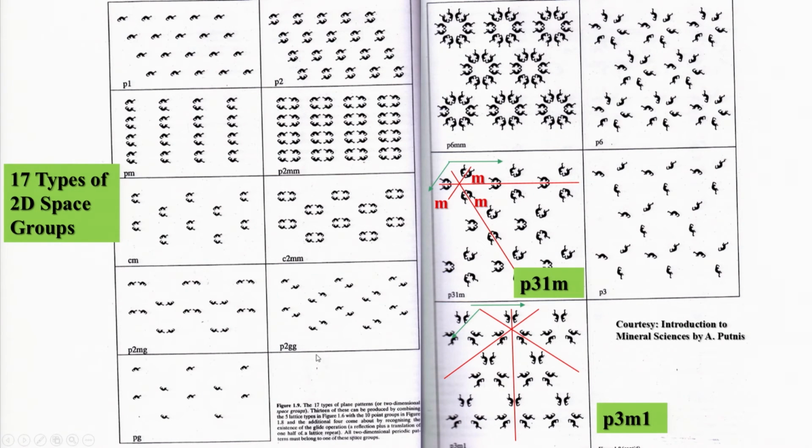And here in this situation, instead of a mirror plane, we now have both planes as glide planes, and you also have a two-fold axis of symmetry. So, you can understand that these two are related to each other by the presence of a two-fold axis, and you can think of one glide plane operation of this orientation, so that after translation this is reflected. So, this pair is produced. Again it is translated along this direction, or after reflection along the glide plane, this pattern produces this here, and in the same way this can be translated along this half unit, and after reflection it generates this pattern here.